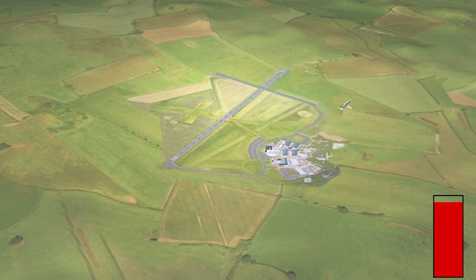What other factors affect endurance? We still haven't considered altitude or wind. Well, the case of wind is quite simple. It has no effect on endurance. You will remember that maximum endurance is concerned with minimizing fuel flow.